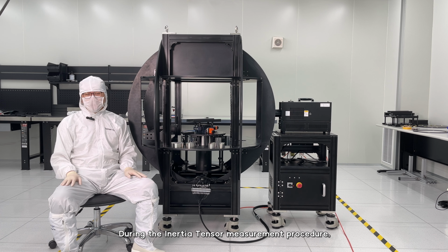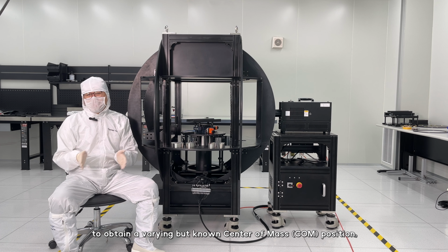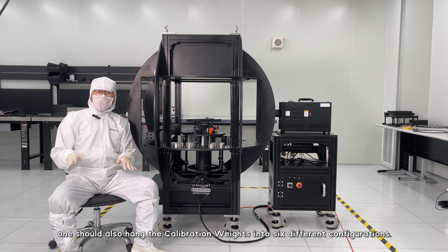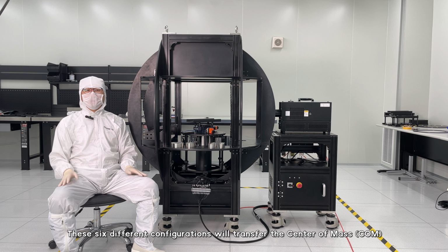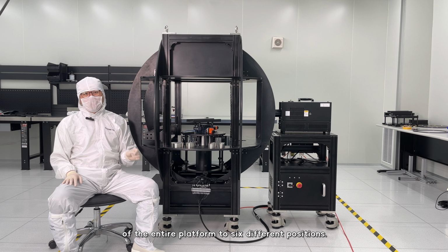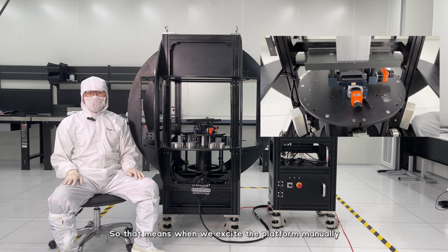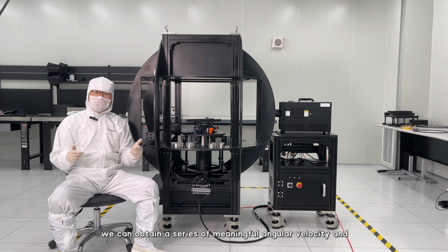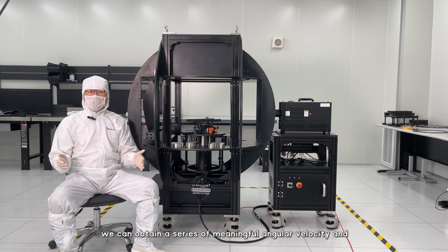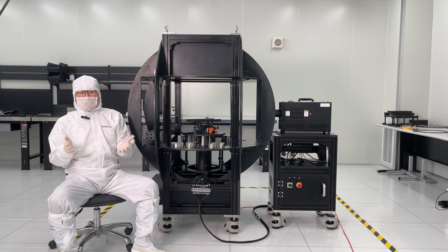During the inertia tensor measurement procedure, to obtain a varying but known center of mass position, one should also handle the calibration weights into 6 different configurations. These 6 different configurations will transfer the center of mass of the entire platform to 6 different positions. So that means when we excite the platform manually by our hand for it to vibrate, we can obtain a series of meaningful angular velocity and acceleration data for us to extract the mass properties.